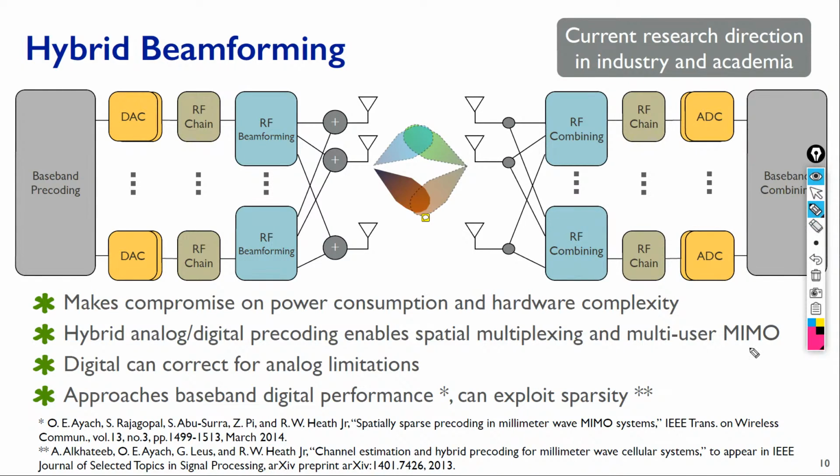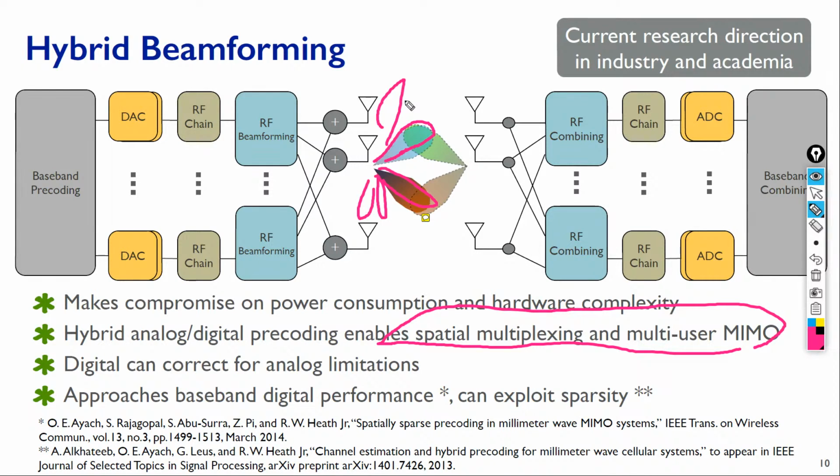This is why we are proposing this technique, in order to serve multiple users at the same time, which can be done by spatial multiplexing. Spatial multiplexing means one antenna, one access point can generate multiple beams, and these beams are not interfering with each other. Each one of these beams can be allocated to one single user that can get connected to it and get the data from the transmitter. So assume this base station and you have multiple receivers, and each receiver is connected with one beam.